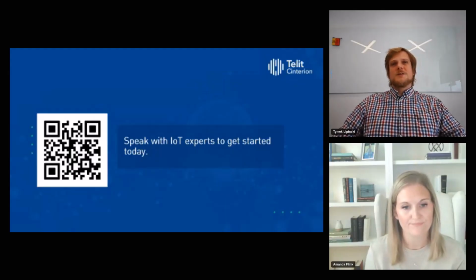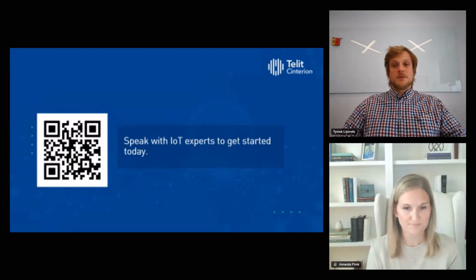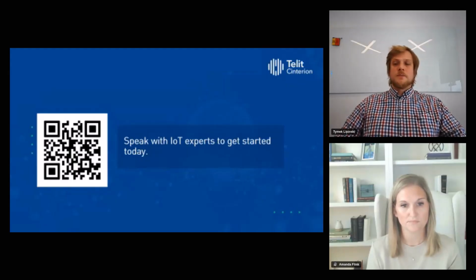In general, when we are sending something over the radio, we have the RRC, which is consuming something between 60 to 400 milliamps of current, depending on the modem radio output power. So when we factor in TLS, DTLS, encryption, it's done on the fly on the modem. Maybe there will be a bit of protocol overhead, but once we have the RRC established, the added current consumption of these extra encryption engines is hidden by the RF consumption. So it does not make a spottable or a visible difference in the current consumption curve and total energy usage.